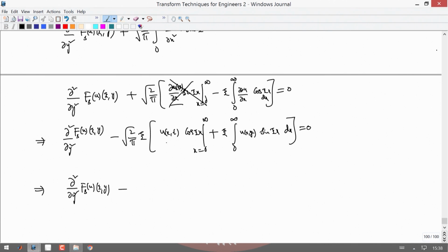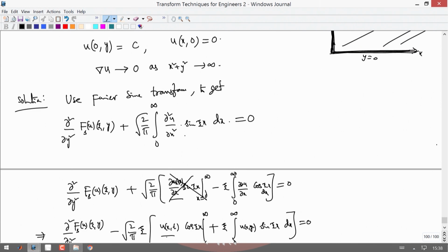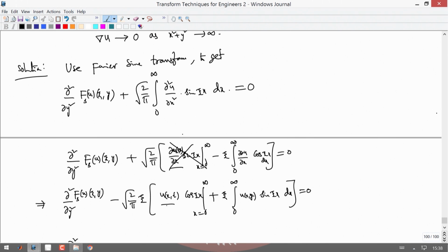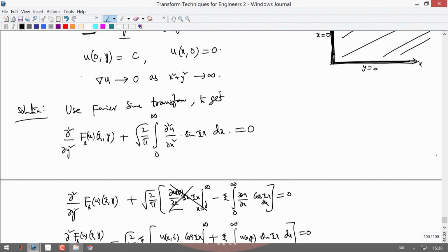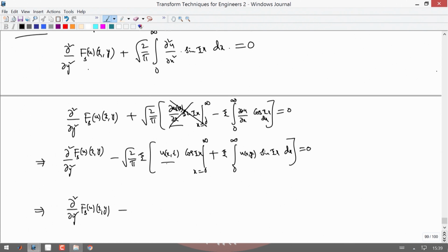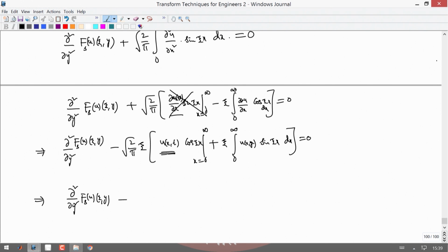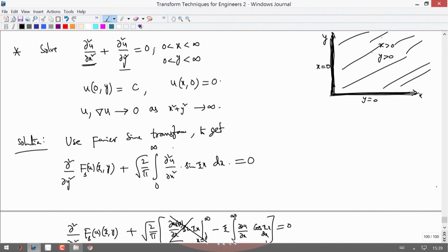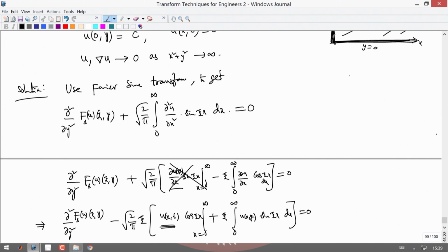minus, again here, this goes to 0 at infinity, the temperature goes to 0. If you apply it, you see that this is also 0, you need u of x, y at infinity to be 0. Even if this is C throughout at infinity, C linearly distributes finally, so that it is in the steady state, that is what you expected. So, if you have a semi-infinite rod with temperature at 0 and L, linearly between 0 and L, you have a linear function between 0 and L maintained.